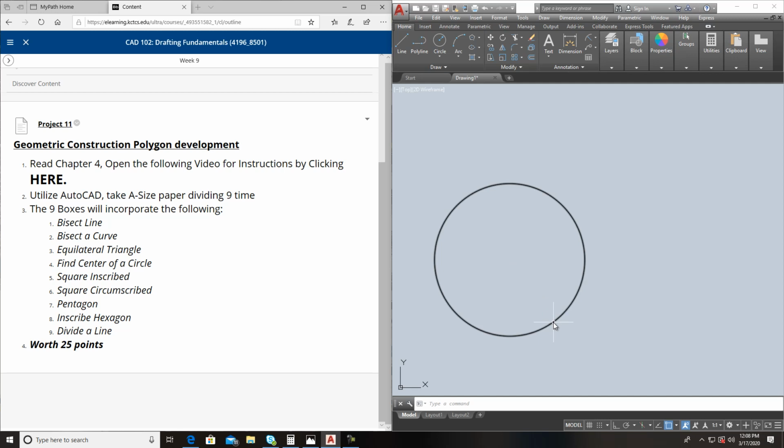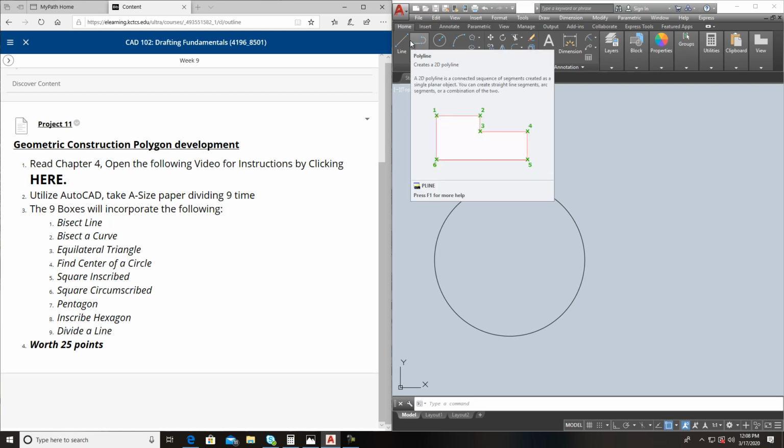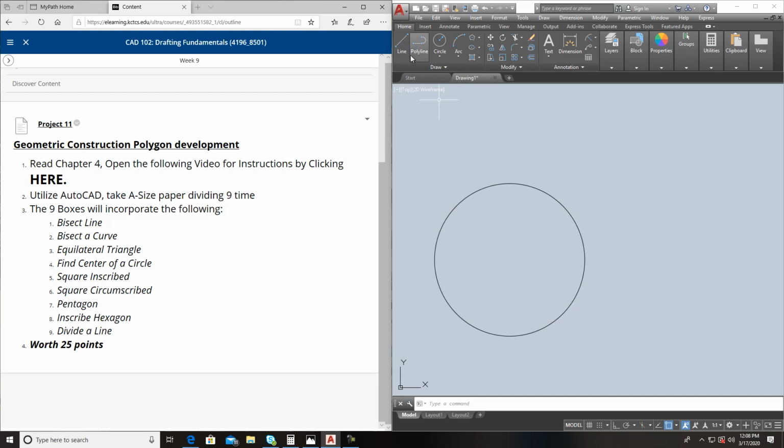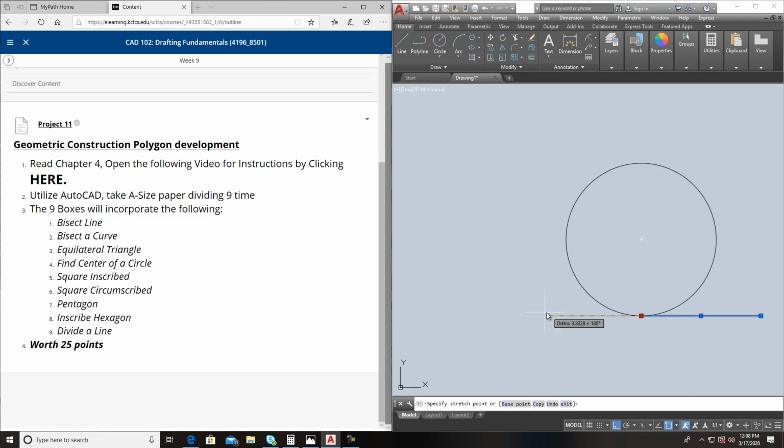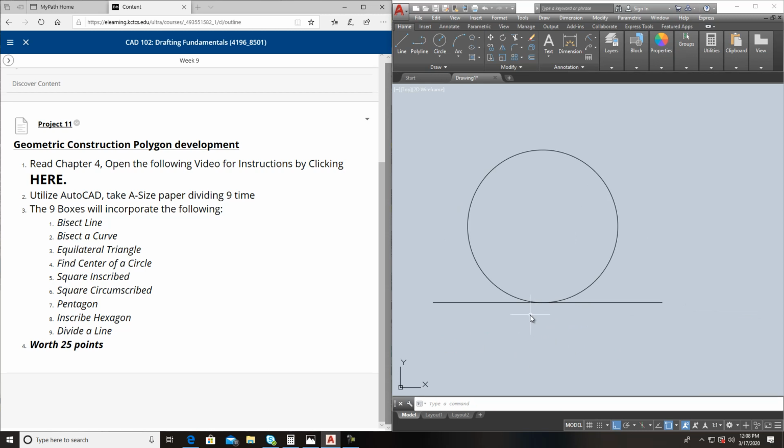For this one, really the quickest way to do this, like on your board, would be get your flat ruler, bring it across on your protractor head, right under that, and then go and get your 30-60 triangle.